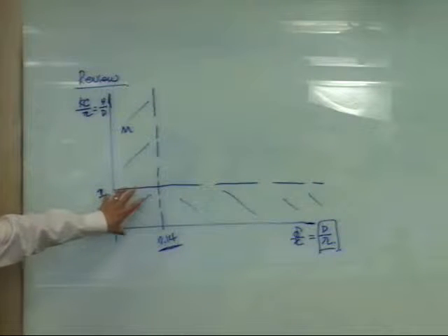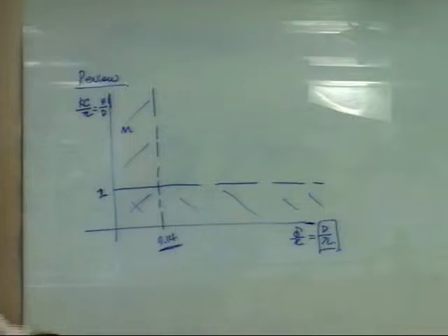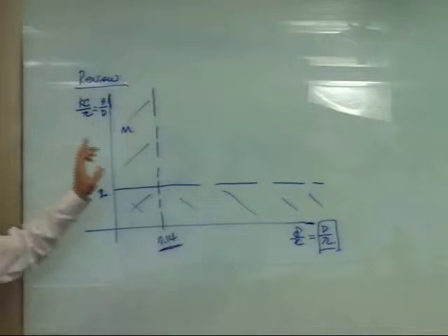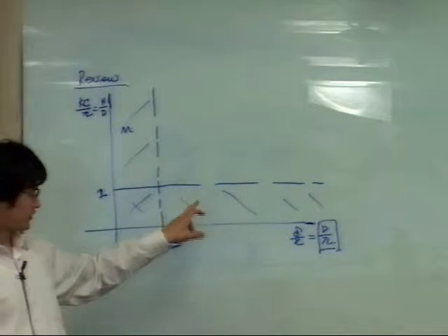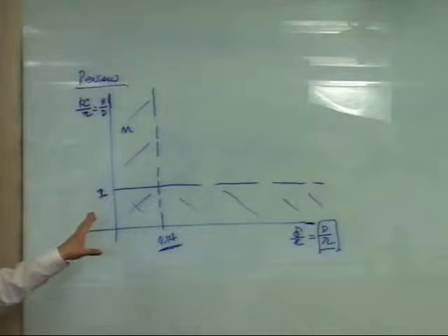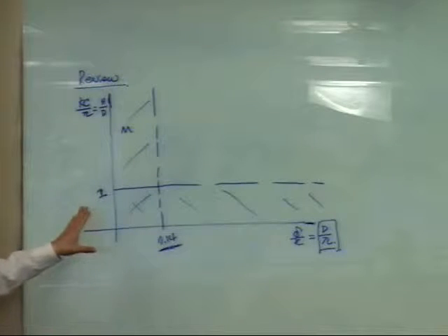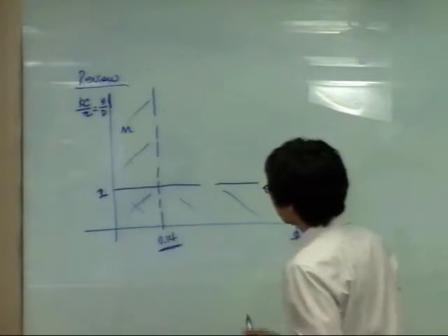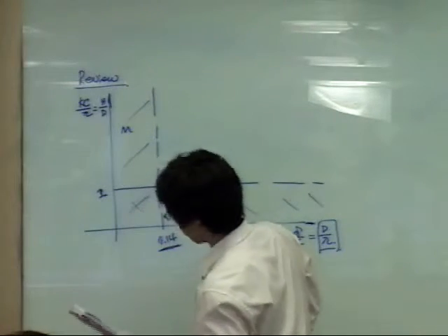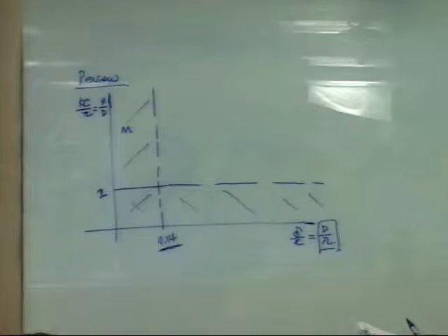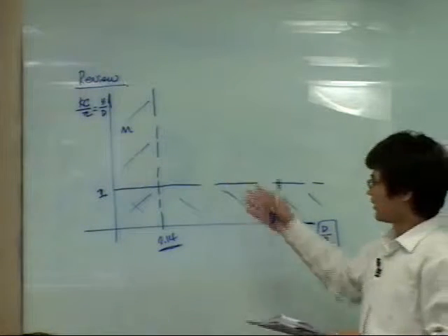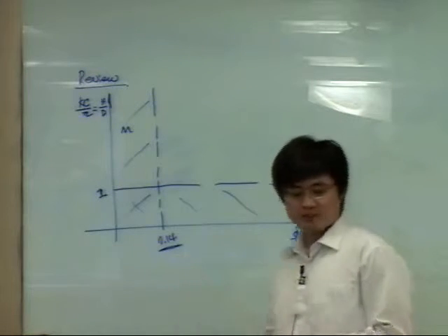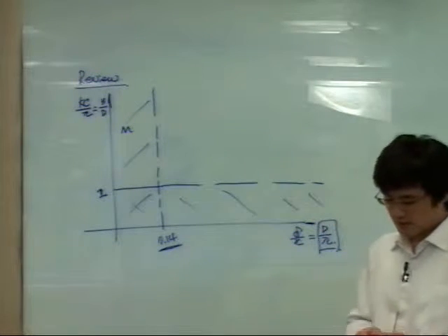So in this small box, we can use both Morrison equation and diffraction theory. In addition, we can also use the Froude-Krylov method. So 3 methods apply in this region. This is essentially the results of a dimensional analysis.